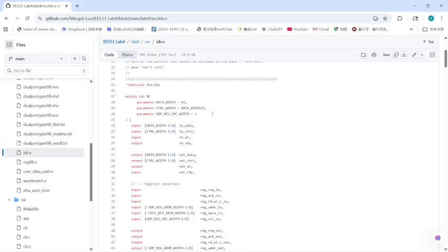The first step requires us to implement the pass-through version of IDS onto the NetFPGA board, which simply connects input directly with output with a wire type variable. This step is not shown right here because our complete version of IDS can be directly implemented on the board. So let's now take a look at the modifications made in IDS.v.